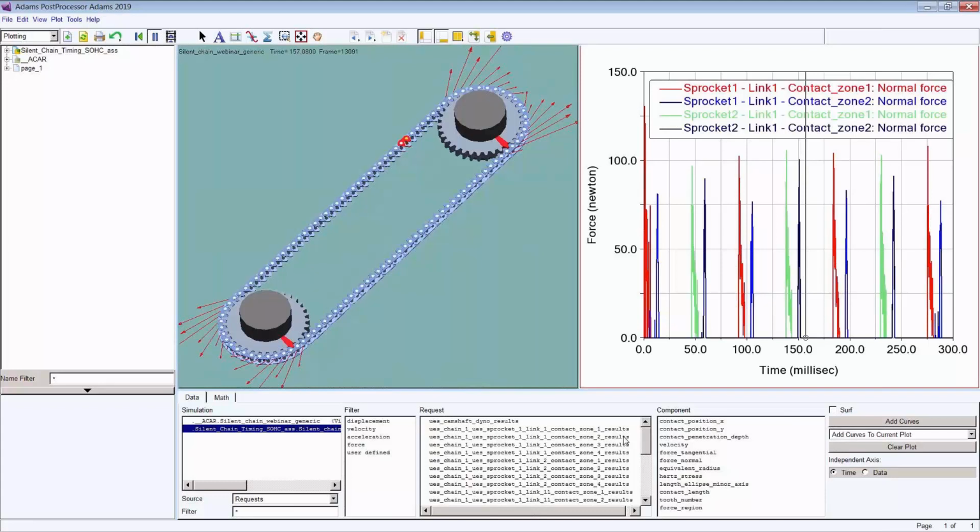So the first question is, what's the absolute calculation time for the inline 6 diesel engine? If it is meant by the EHD model that has 7 main bearings modeled as elastohydrodynamic, it's a very high fidelity model. If you run it on a laptop with a single core, it took about 11 hours. If we run the same model with 8 threads, it took only 3 hours. So it is in the order of hours, but it is a very high fidelity, complicated model.